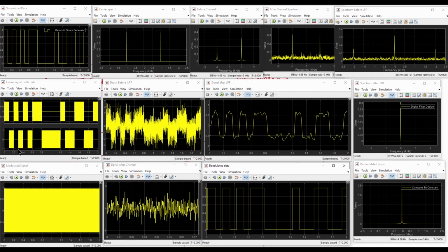And if you see all the spectrum, this is the carrier spectrum, the 1 kilohertz carrier spectrum, and when these two are added, the value of the RMS is getting less over here, and after adding the noise, you can see there are lots of spikes at other frequencies also. But our main target is to detect this one, and that's why we modulated this signal to increase the value.